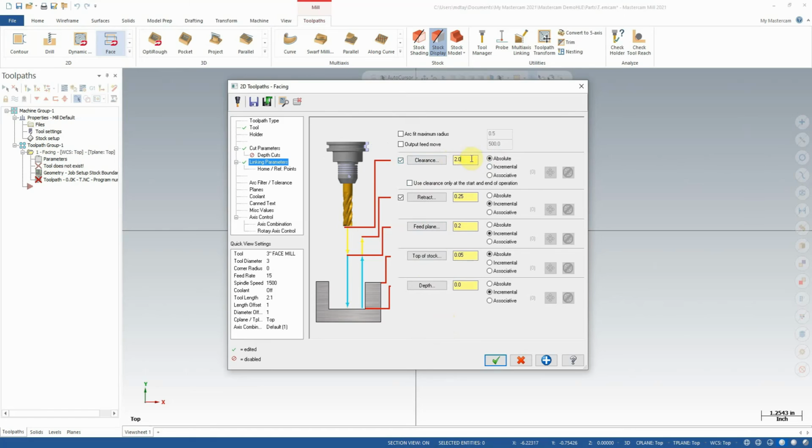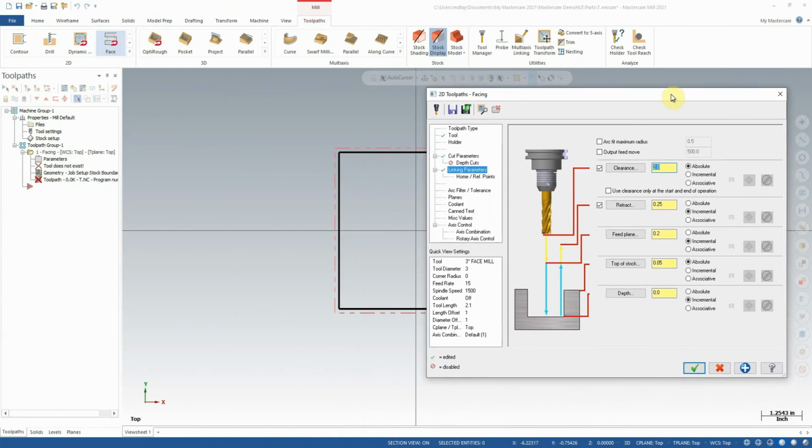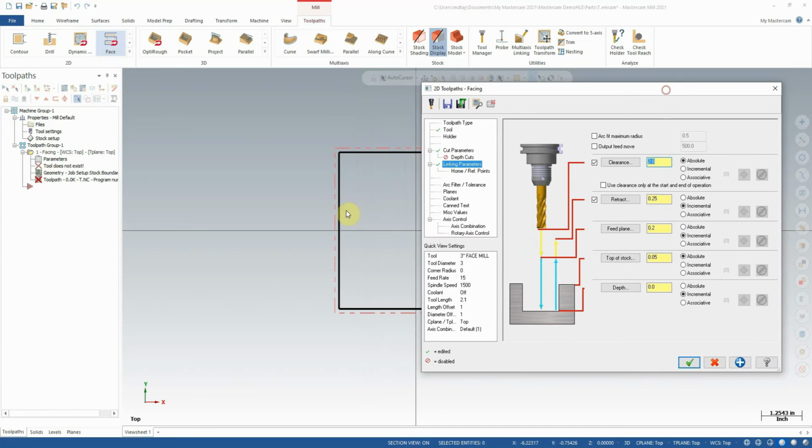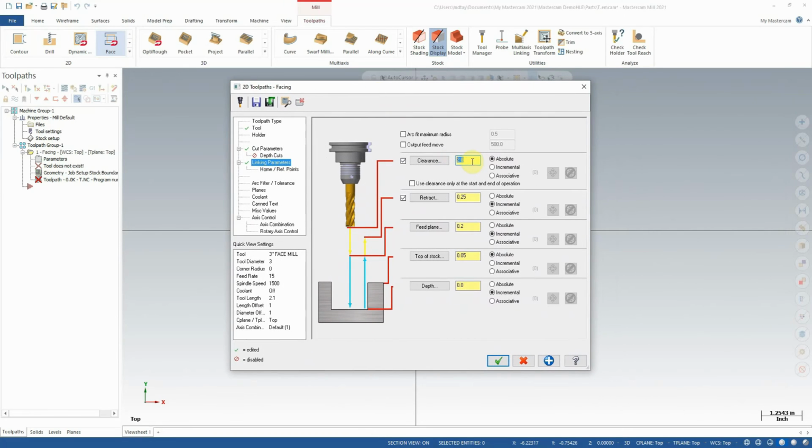Generally, a 2-inch clearance is a little bit of overkill though. Again, this will depend on your part. For our purposes though, and for the way that I've programmed this part, keeping in mind my preference is generally to program in the negative z-axis, any number I put in here, I know will be above the part regardless. Even if I only put 100 thou here, it's still always going to be 100 thou above the part. Now for safety and for not pushing limits right now, I'm just going to set this to 1 inch, which is plenty of space, at least in my opinion. 1 inch clearance above the part is more than enough for this application, especially considering we won't actually likely be machining this.